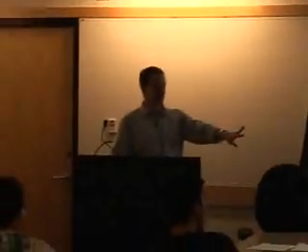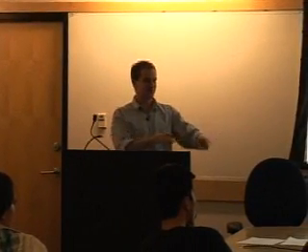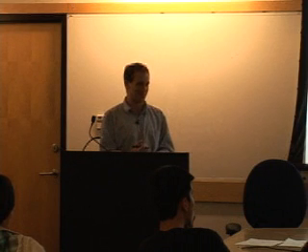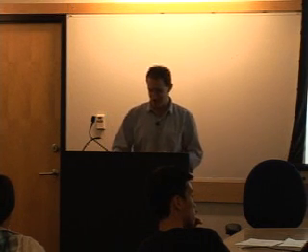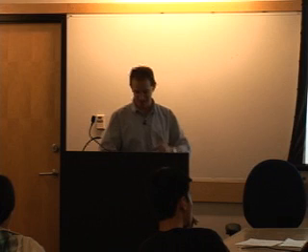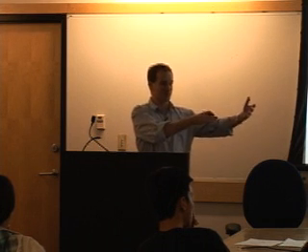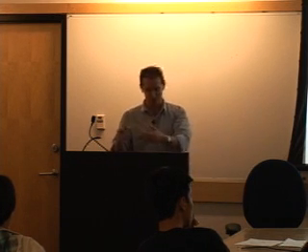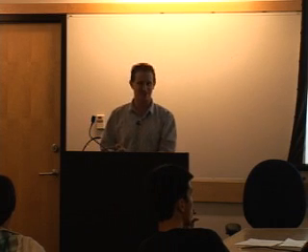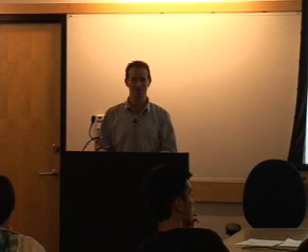This is the input referred noise of the original amplifier. So this is like the input referred voltage noise of the amplifier. This is the input referred current noise of the amplifier. Exactly. Well, the box is exactly considered ideal, except that these input referred sources are due to the box itself. But in this model, the box is ideal. Good question. Other questions on this?